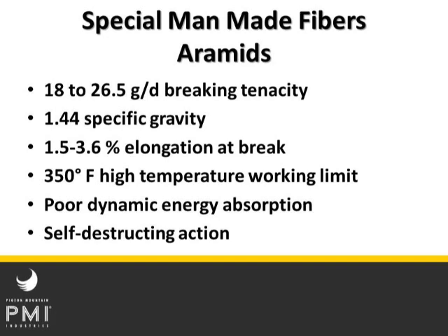As you bend it back and forth, it kind of abrades on itself, which is why it tears up so fast. If you talk to police with Kevlar vests, they will tell you how often they have to replace them, because the flexing and normal wear and tear just wears them out pretty fast.